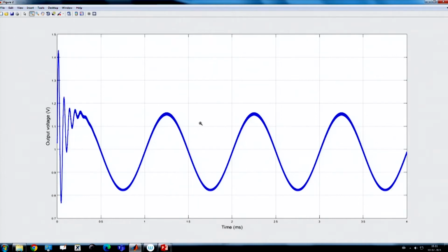That means if there is any disturbance in the source, and we saw in the previous lecture, due to the supply impedance or due to the interconnected converter, if there is any sinusoidal or any periodic excitation, or even a damped sinusoidal that appears in the source, that will be propagated to the other converter which is connected to this source, provided it is just in open loop control.